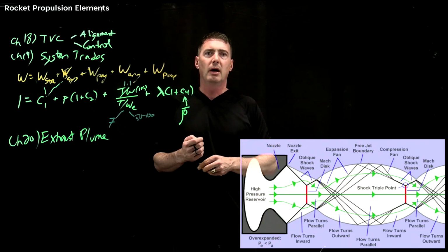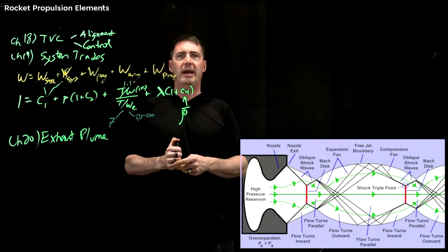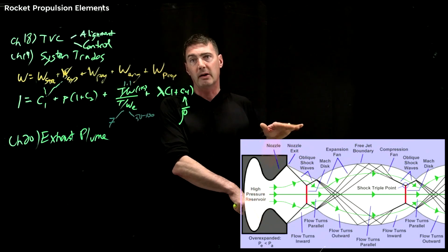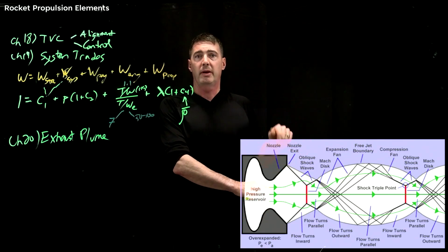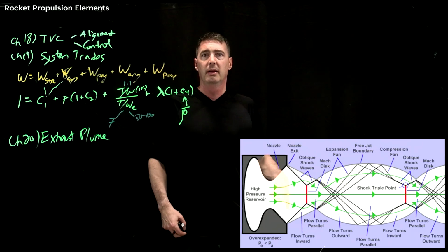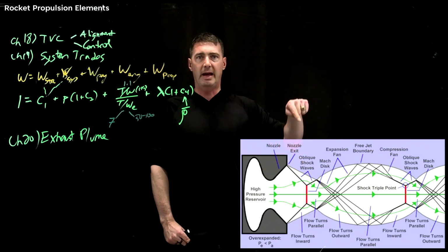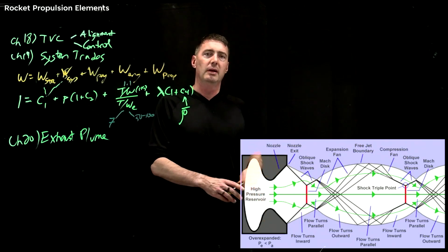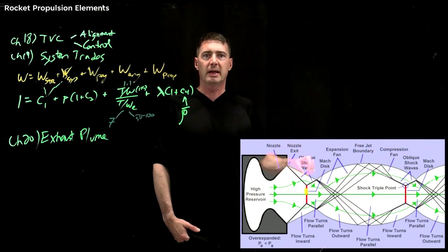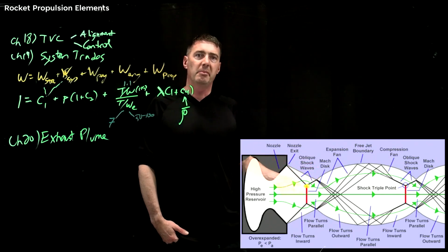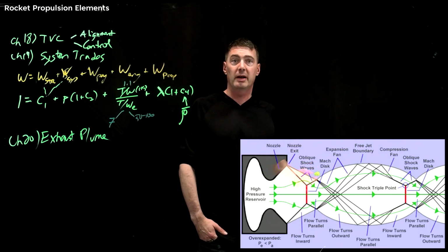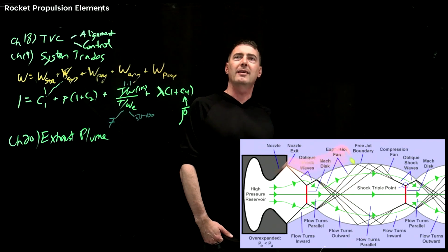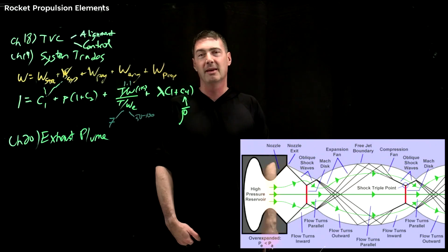So I'll just show you, when you see these shock diamonds, what's actually happening is usually a rocket engine whose nozzle is designed to work at higher altitudes, but you're at sea level. So here you're actually low pressure, and that's going to create a shock wave, and then the atmosphere is going to push back in. If you're sonic at the throat, you become sonic again here. And so the flow is turning, but now you've got high pressure, you got over compressed, and so now you re-expand through all of these shock waves, and then it turns back. It makes for these really beautiful shock diamonds.